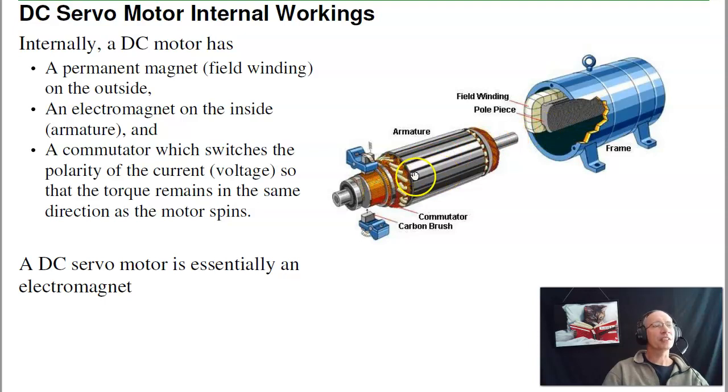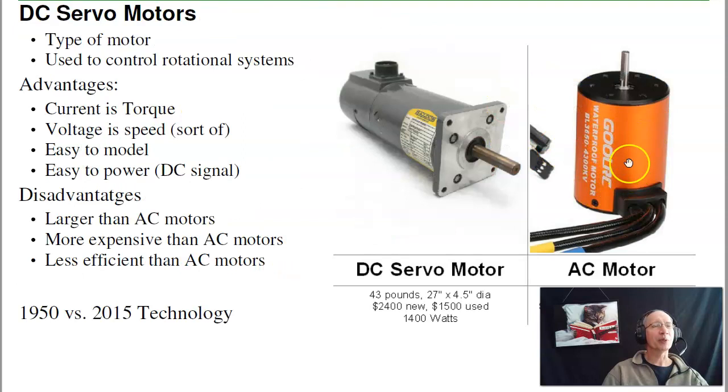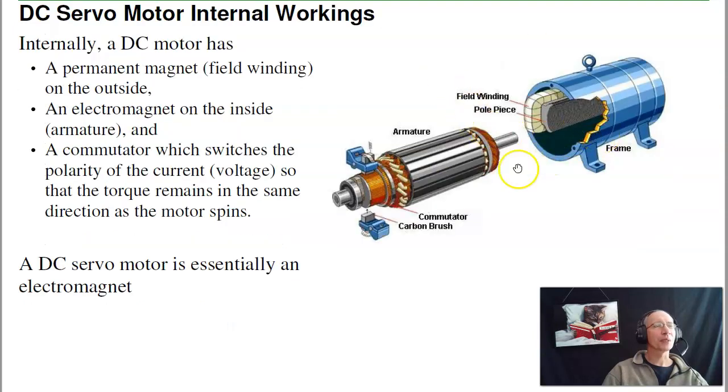The cost, however, is I actually have, from this figure, looks like about a dozen motors in one. Only one of them is energized at any given time. All the other windings are basically wasted. So there's extra weight, extra cost. Plus they lose efficiency. When I take the coil and disconnect it, I've got energy in the inductance as 1/2 Li squared. As I disconnect it, the energy gets dumped to ground. That causes a spark. That jams the radio frequencies, gets the FCC upset. To keep the FCC happy, I have to have this big metal case around the DC motors. All that adds cost, weight, inefficiency. Get rid of that, go with the AC motor. I can make the motors much smaller. But that's how DC motors are built.